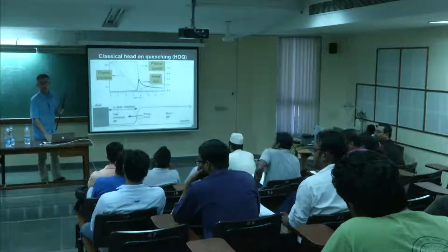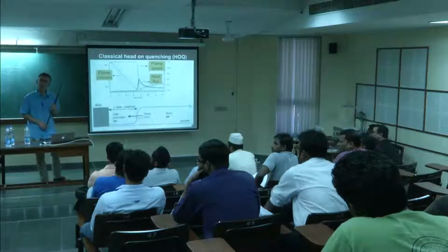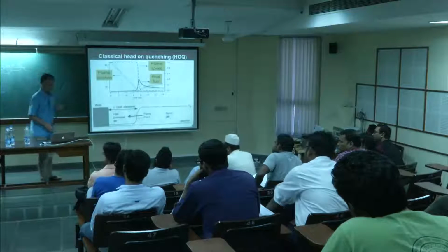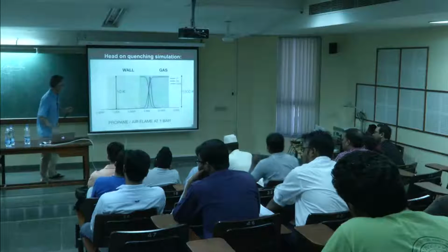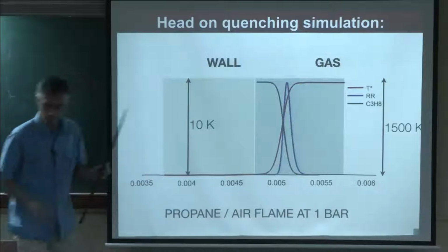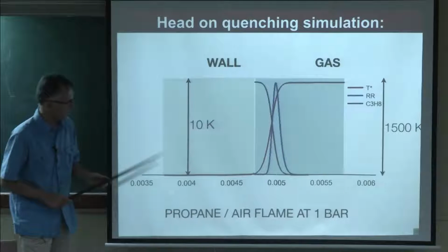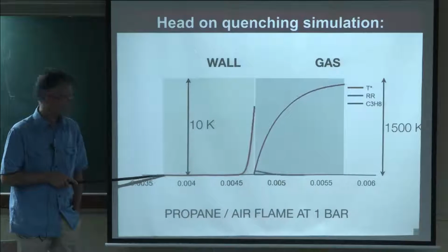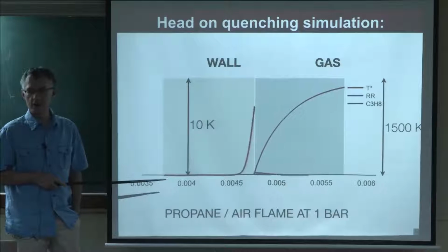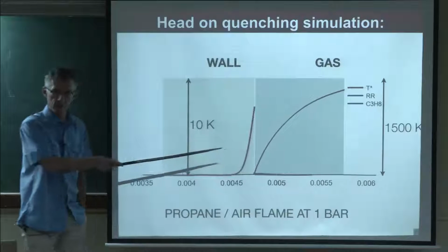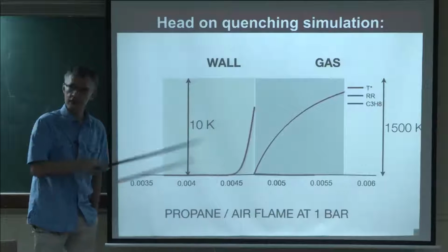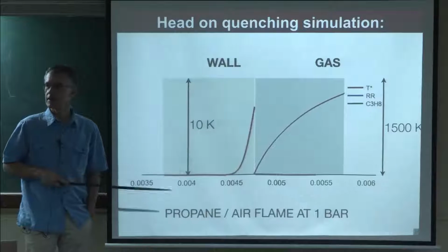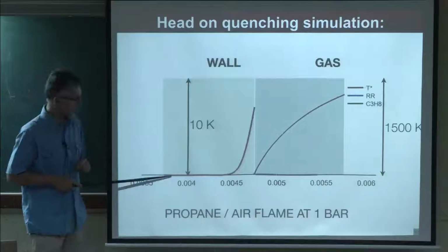What should be the boundary condition that we should apply on the wall? Here it's isothermal, but as you can see, it does not play a role for this first case because the perturbation of temperature has no time to reach this wall. So you can use iso-T or adiabatic, the same. If you repeat now this interaction 2 times, 3 times, then it gets more complicated. But here it's only one shot, so you can say constant temperature.